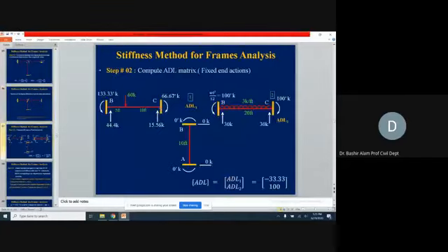So this is how we now split them at joint B into fixed ended. Here you see P B A squared and P A B squared divided by L squared. That equation we are using in finding out these fixed end moments. Reactions we found, you can verify these from the fixed end equations.